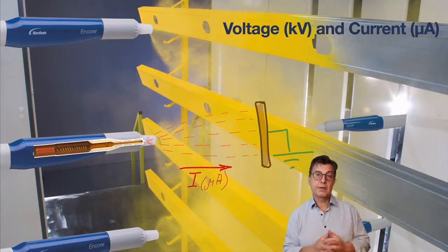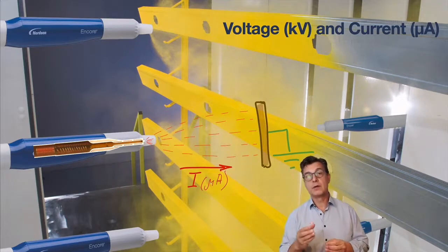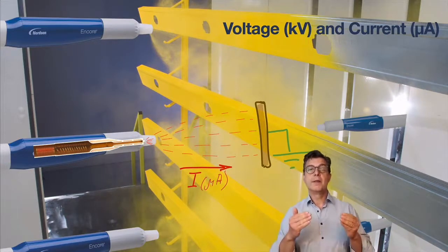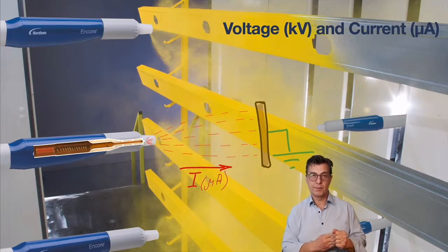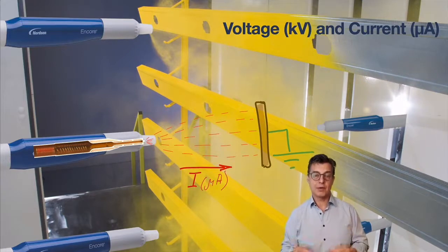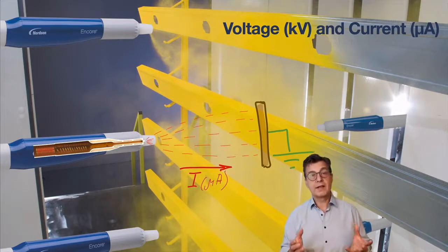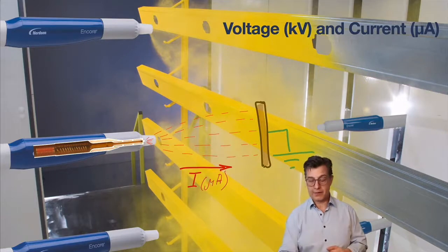Well, not a single system on the market actually shows the kV at the tip of the gun. When you set the voltage to 50, 70 or 100 kV, you're merely setting the percent of the maximum output. We cannot measure the actual kilovolts at the tip of the gun in real life situation. So what is then the real kV at the tip of the gun?